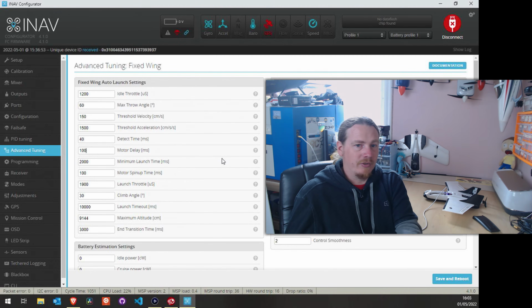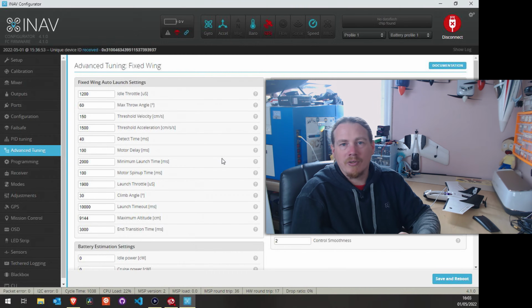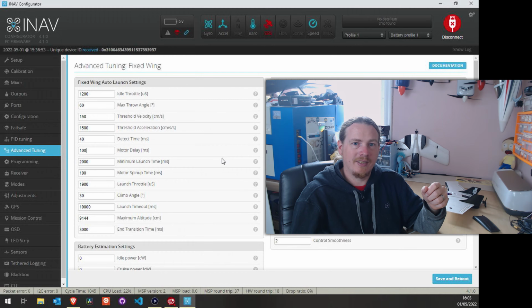Also, if maybe you've got it on the ground, you pick it up, you knock something. So depending on your situation, how you fly, you may want this on, you may not. If you do have a problem with the launch, however, the only thing you can really do is disarm it. So that's one thing to take into consideration. If you do have a failed launch or it starts going off in the wrong direction, the only thing you could really do is disarm it. If it's high enough, you could probably rearm it and take control back. But again, it's one of these things that you need to set for the best outcome for most situations.